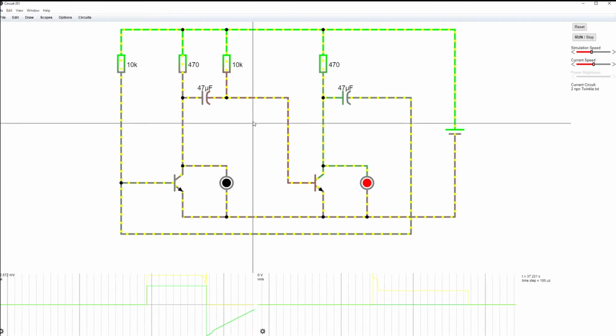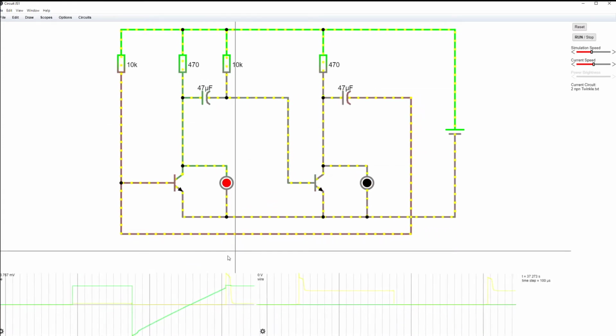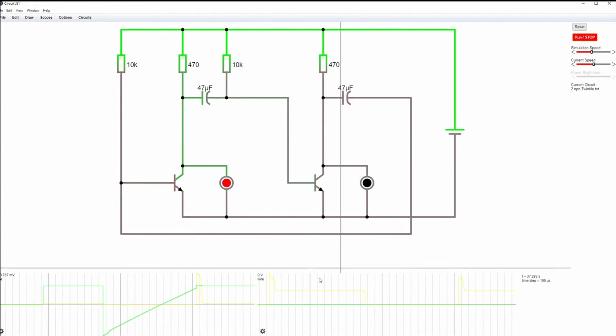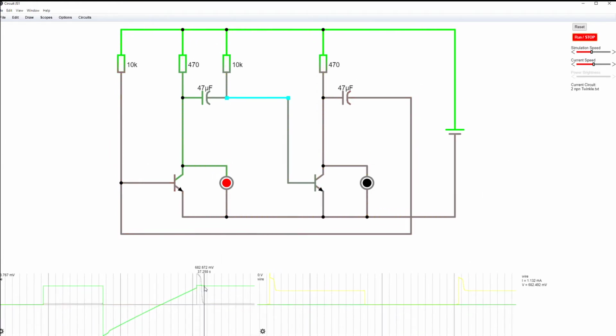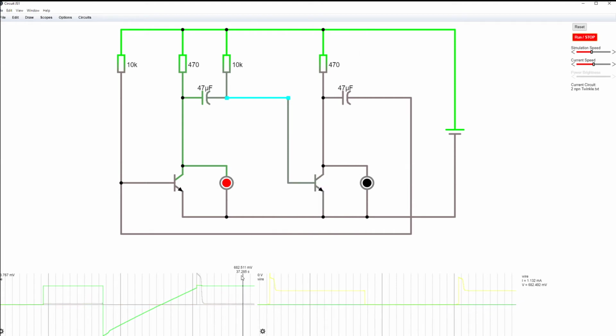Let's have a look. Over here, the voltage is going up, and then something drastically happens. Once we get to a point where it gets to about 0.7 volts, that's when the switchover happens in the system. We can see that 0.7 volts, which is 37.2 seconds, should line up with this 37.2 seconds, the current instantly starts flowing through this transistor.